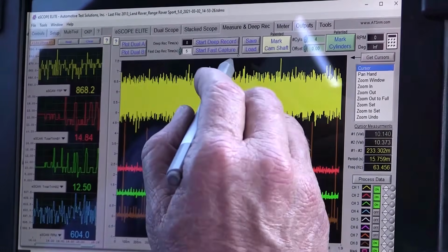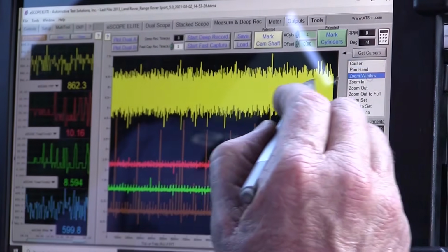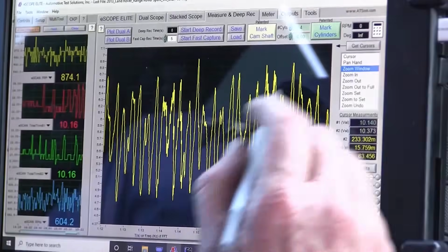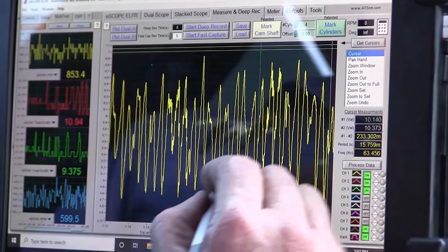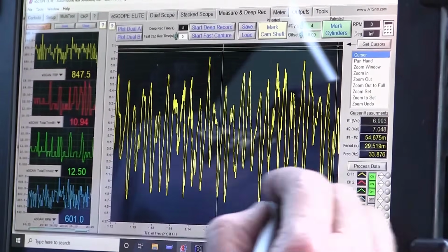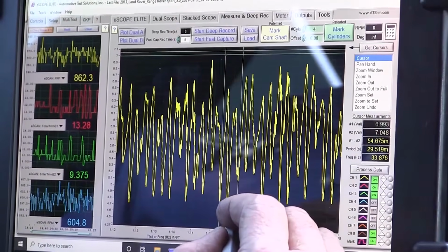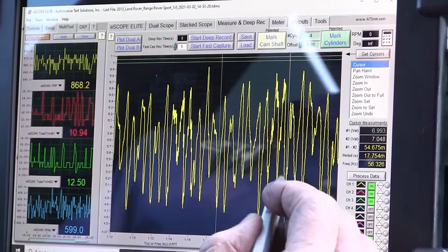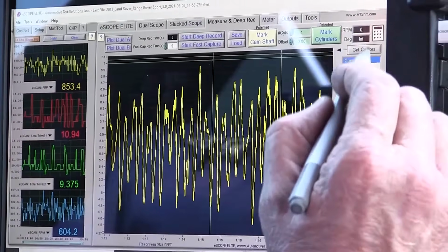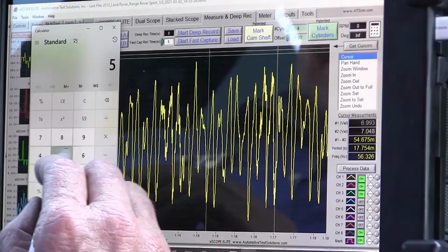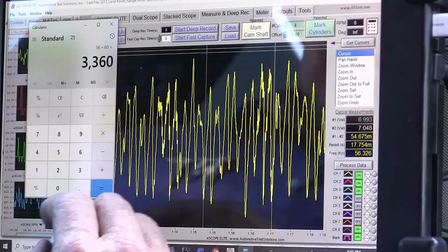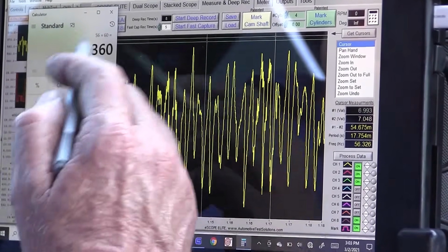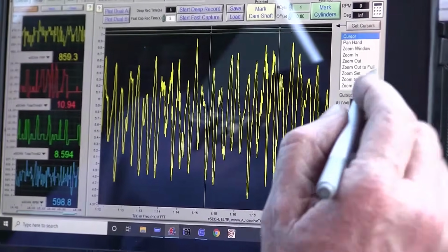Total trim and the other are close. So now we want to zoom in here, and I want to do the 8 bars again. We pick a bar, and that's 1, 2, 3, 4, 5, 6, 7, 8. Again, we have about 56, so you take the 56 times 60, that's hertz to revolutions per minute. So we have about 3,300 RPM, and that's about what I would expect this pump to make.